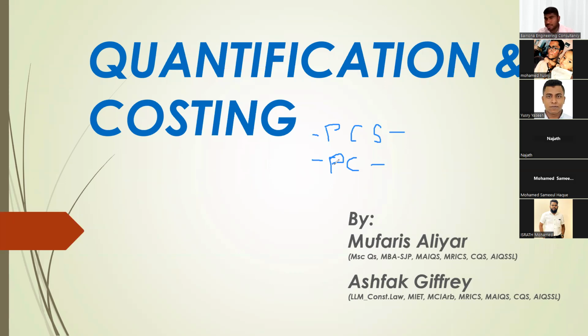What I found is that in the UK contract they allow this prime cost sum, for example, for connection of water or connection of electricity. It's like the provisional sum we use here. But here what we use is a PC rate, prime cost rate. This is not a sum, this is only a rate.